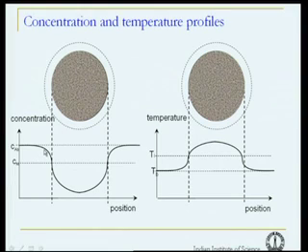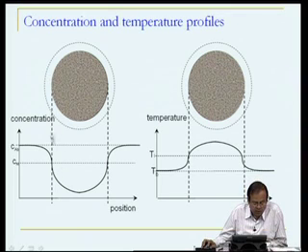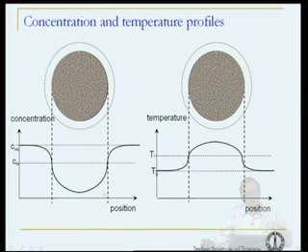So, what happens here is the concentration far away from the surface of the catalyst is the bulk concentration. It reduces to surface concentration CAI because of resistance to the mass transfer outside the catalyst, and then the concentration decreases gradually as we move from the surface to the center of the catalyst, and being symmetrical, the same thing can be seen from the other side as well.